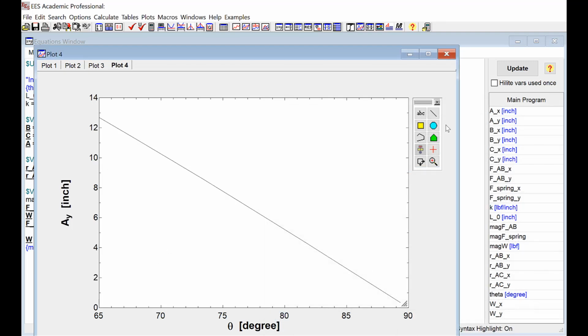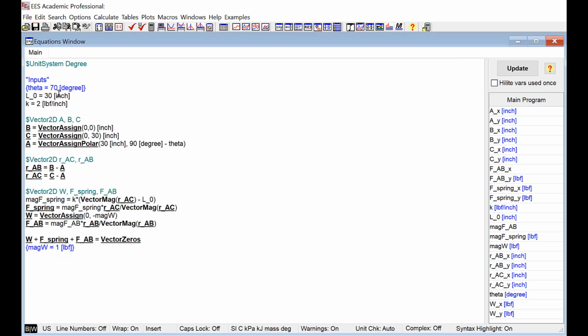So if I wanted to design one of these things, right, I might have some specification that 15 pounds should move my tool 10 inches. I could now do things like change the spring constant, K, or change the free spring length, L, or the geometry, these 30 inches, in order to hit some kind of design considerations. And that's where you're really going from kind of a textbook problem into the real world, where you actually have to design a mechanism to do a certain job.